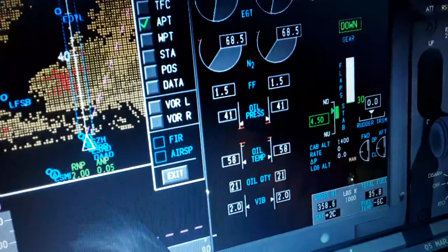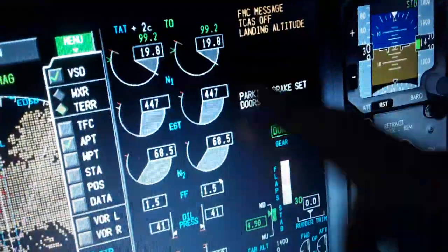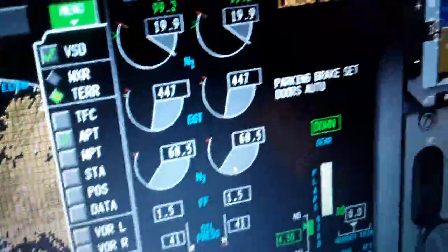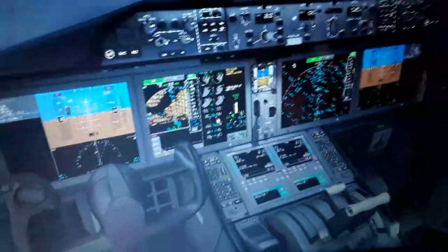Also the engine indications from the FADEC, the Full Authority Digital Electronic Control computers. So we have the FADEC, the Full Authority Digital Electronic Control computers, one installed per engine gearbox, dual channel redundancy, one channel fails, the other takes over control, multiple displays all the engine data, using the upper and the lower EICAS, engine indication crew alerting system display, or multifunction display.